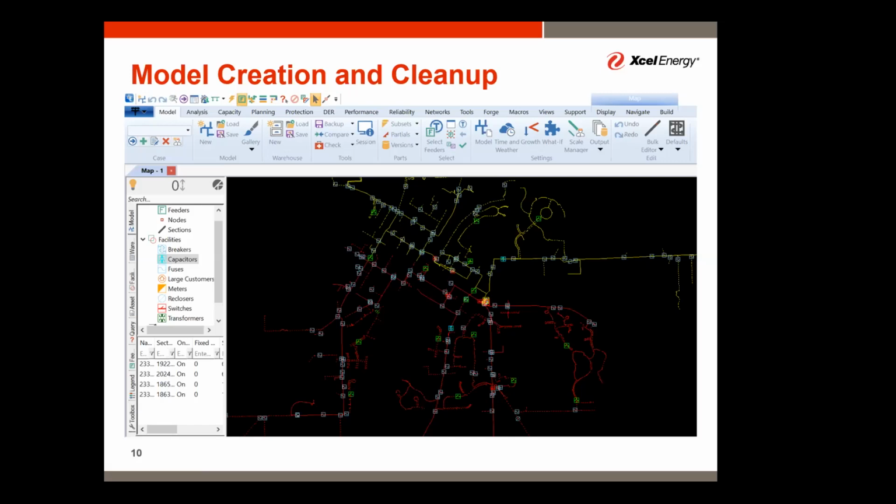If we were able to zoom in, we could see that the model is comprised of a large amount of nodes. These nodes are essentially subsections of feeder with a section of conductor in between. Often the overhead nodes are notated by power pole location, though nodes can be somewhat arbitrary in terms of position, but they essentially act as subdivisions between sections of feeders so that different sections can be edited.